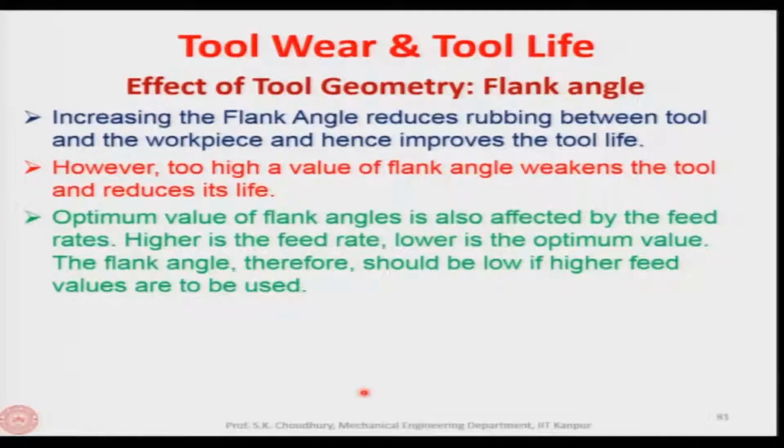Now, the flank angle. Increasing the flank angle reduces rubbing between the tool and the workpiece, and hence it improves the tool life. However, while increasing the flank angle, as we have discussed earlier, the cutting angle reduces and the tool again weakens, which reduces the tool life. The optimum value of the flank angle is also affected by the feed rate. The higher the feed rate, the lower the optimum value of the flank angle. The flank angle, therefore, should be low if higher feed values are used. So, these are the recommendations which are obtained theoretically as well as experimentally.